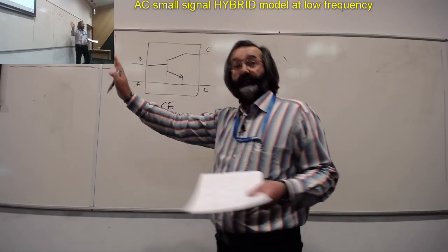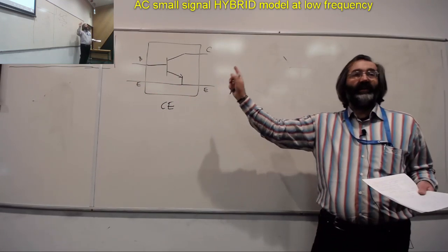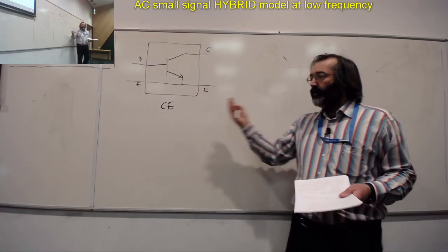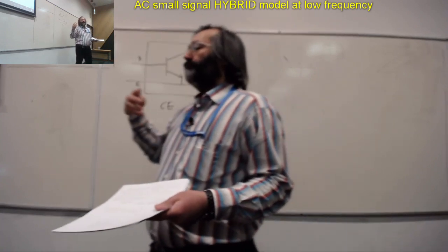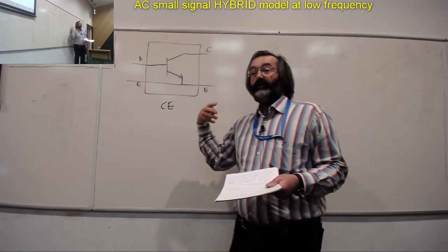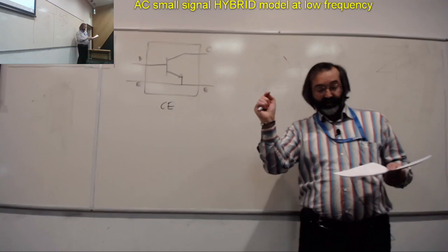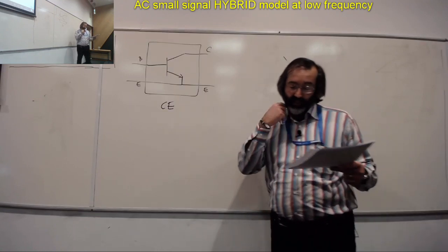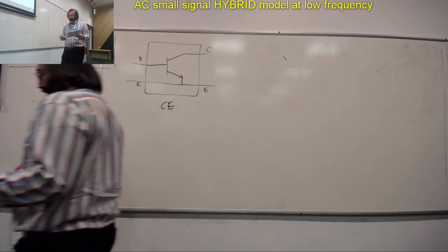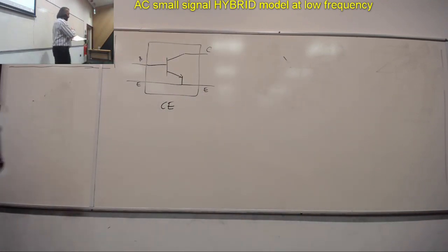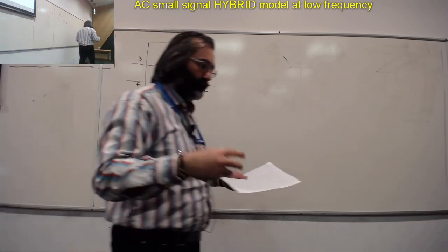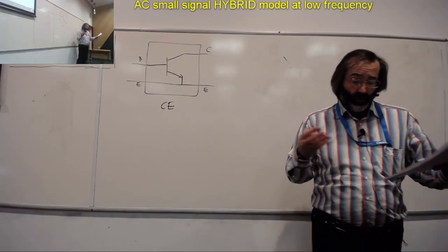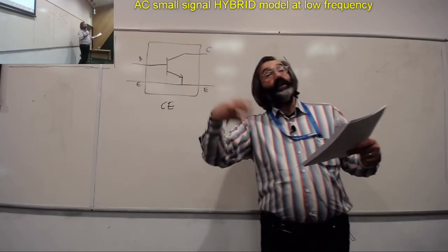We've defined ways on how that could be easily done. So that's solved. We know how to place this in a specific quiescent point. So now the idea is to linearize this nonlinear component just around the quiescent point. If you want to have a look at this AC small signal model, the principle, we've done it before. We did it in chapter 1 when we introduced the concept.